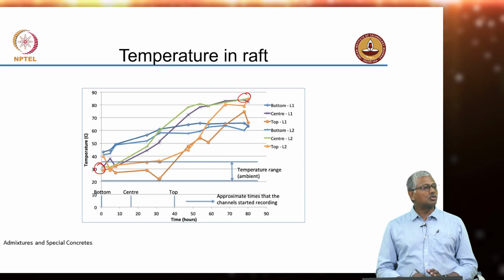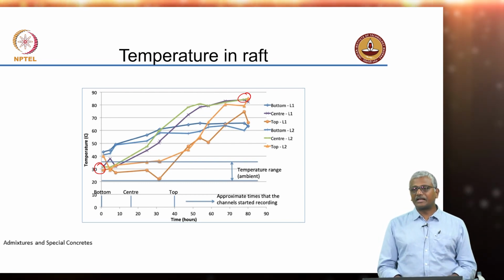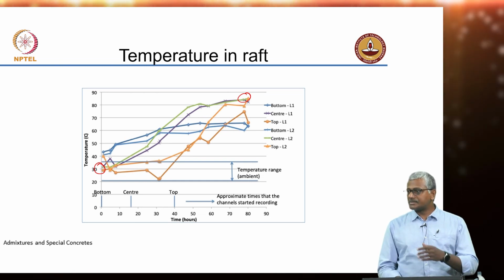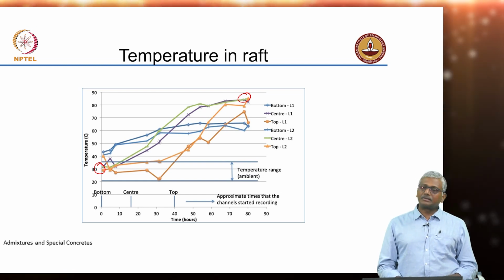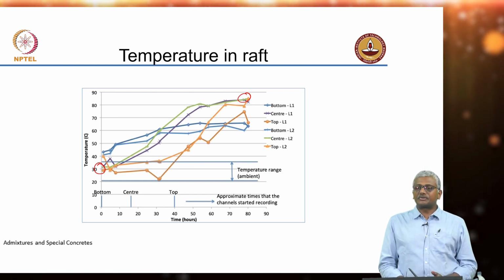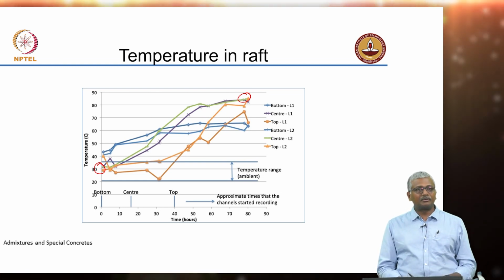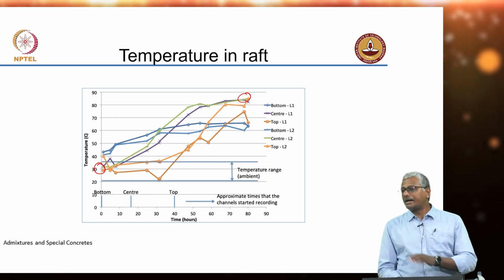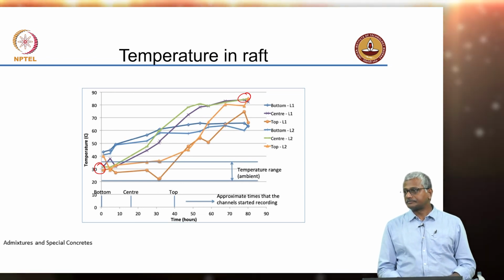The first and foremost step in designing mass concrete is to lower the placement temperature as much as possible. In job sites where there are significantly large quantities of concrete to be delivered, it is almost absolutely essential to set up an ice plant to ensure that you can actually use ice for preparation of the mass concrete. Deliver concrete at as low a temperature as possible.